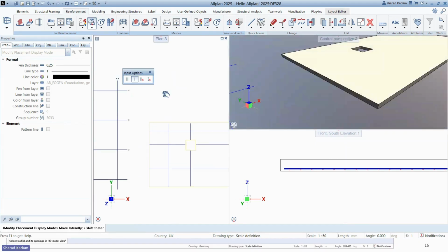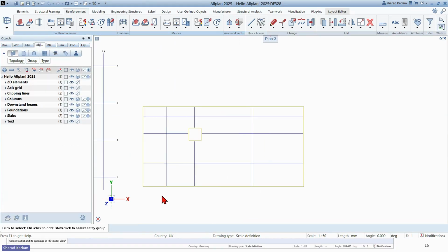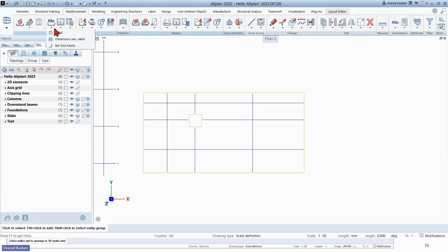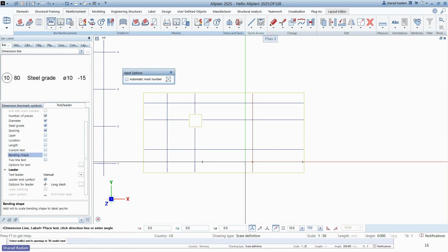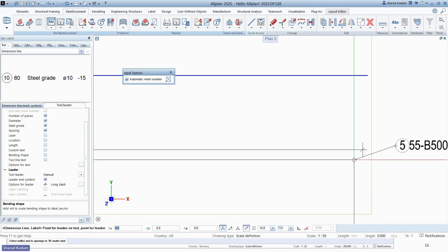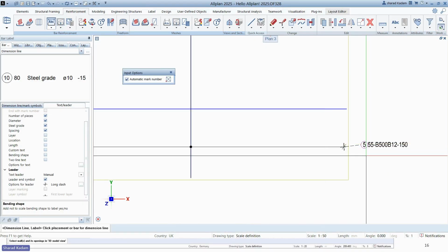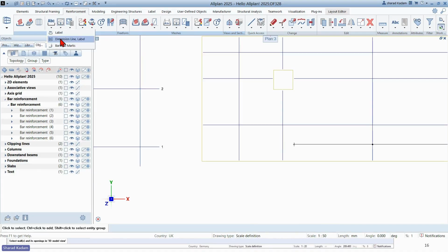So what we are seeing in this plan section is plainly for the rebar portion or the detailing portion. So once this is done, we can go for the dimensioning portion. So I can just put on my dimension over here and it can be tagged. So tagging can be done like this, or as per the choice, we can do it. And the command can be still active.